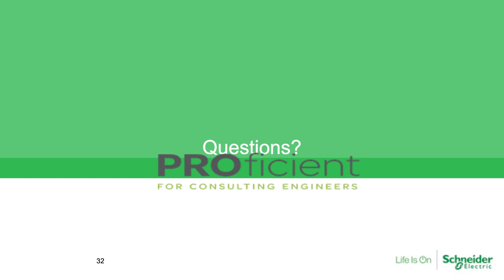There is a question number 5, Duke. If you're already using a power meter, why would you also need to use embedded breaker metering? Oh yeah, that's a great question, and that question comes up a lot. Effectively, you have a meter which is often mounted upstream from the breakers that circuit is feeding. And so the meter is often used as a critical power analysis tool. The metering information that comes from the breakers is a lot of times based around energy awareness and the status of the breaker.